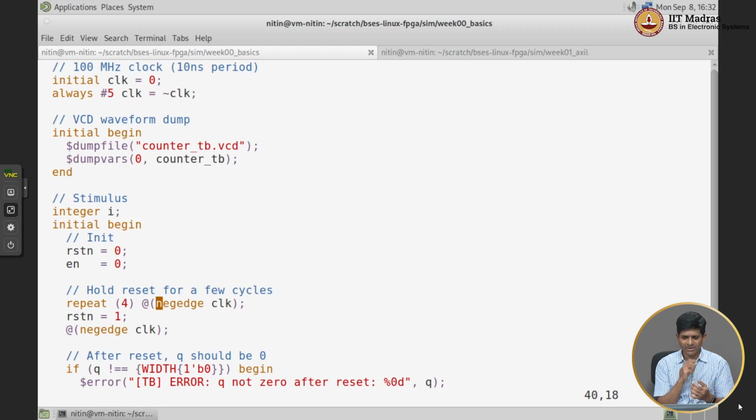And sometimes, because these two are separate Verilog modules, the simulation gets into a wrong state and does not handle them the way we would normally expect. In other words, it does not properly finish up all the processing before coming back and doing the transitions on the reset.